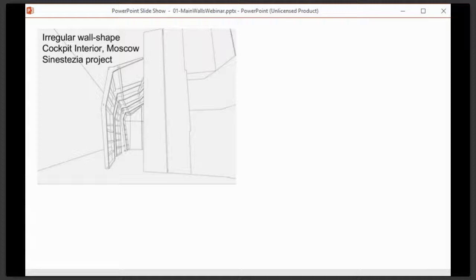And lots of the time, they'll actually have details of the plans of any building that you're looking at to renovate, or if there's a group of houses in an area, they will generally have details of them that they can say to you, okay, all of these houses were designed like this. These are not load-bearing walls, so you can go ahead and make changes, or they'll say, no, these are load-bearing walls. You'll need to consult with a structural engineer. So you cannot touch a load-bearing wall without consulting with the structural engineer. You can design the layout, you can come up with the design that you want, but the design of the components has to be carried out and calculated by a structural engineer. Okay, I hope that makes sense.